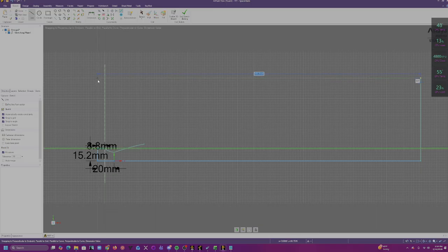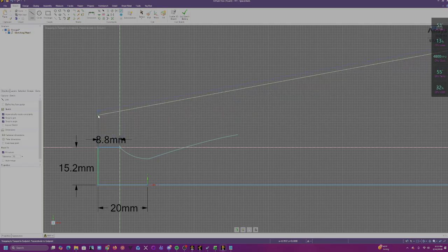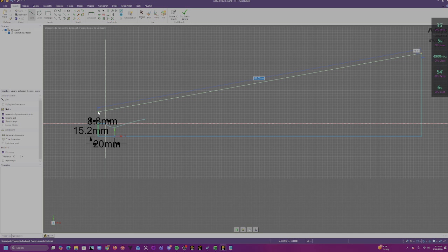All right. By the way, if you want to be perfectly aligned with other lines right here, you can hover over this point right here, and you can see there's a dotted line, which indicates that you are directly at the same length as the line you hovered over. So all you have to do is that, and then click, making sure it's at 90 degrees, so it's perfectly flat. Click that, and then go ahead and press escape.